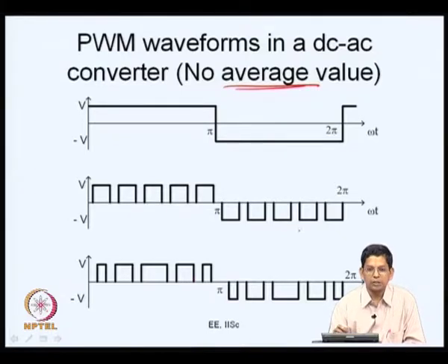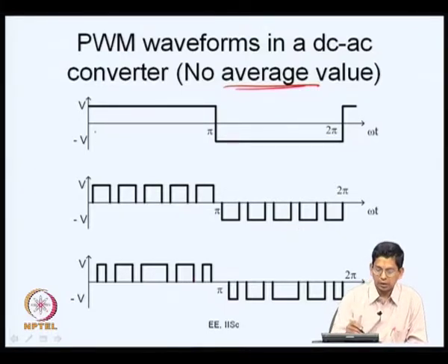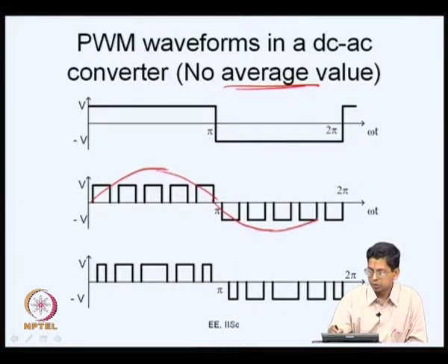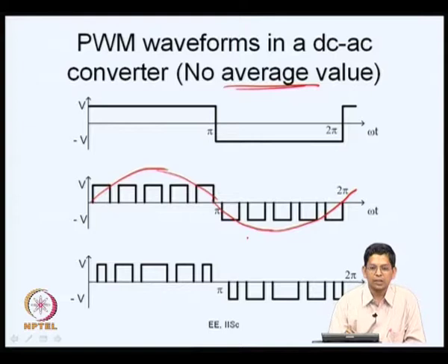Ideally we wish that they were sinusoidal waveforms. So, what we want to see here is some sinusoidal waveform like this, but then it has several other non-sinusoidal components which we cannot help because we are producing AC using DC. We are applying basically positive DC pulses and negative DC pulses to get something like this.